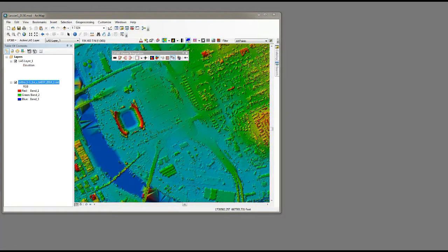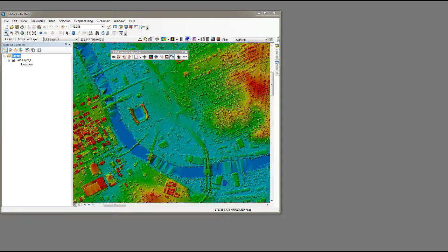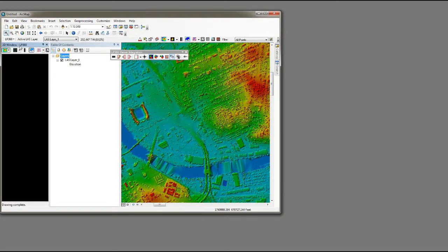I'm going to use LP360 for ArcGIS for this demo so that I can show you how the GIS Fusion works in the 3D window. I'll start by clicking on the toggle in the LP360 Viewer Integration toolbar. The 3D window comes up docked, but it's not in a very convenient orientation, so I'm going to go ahead and undock that right away.